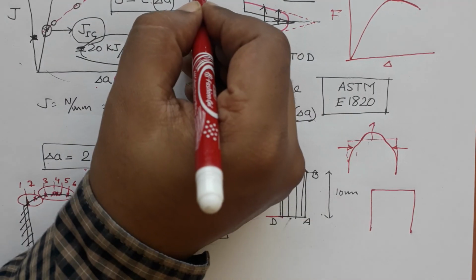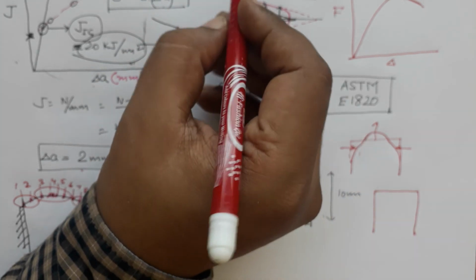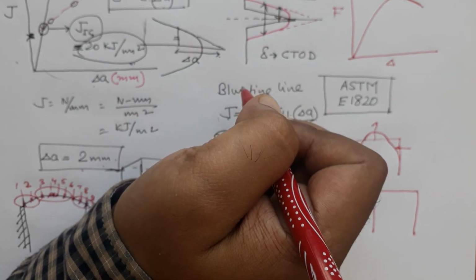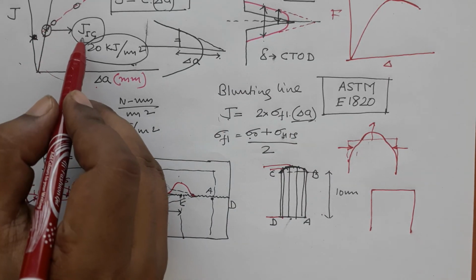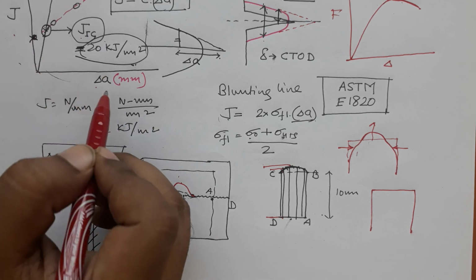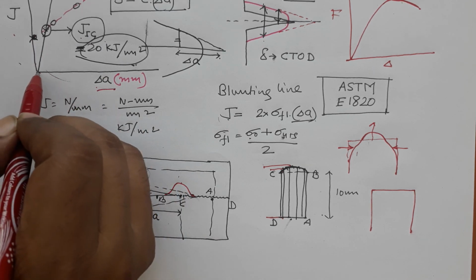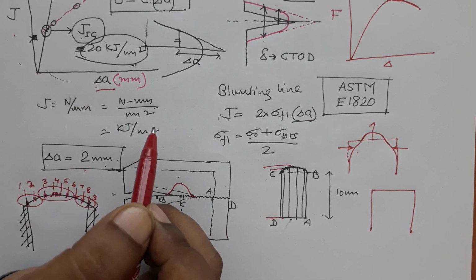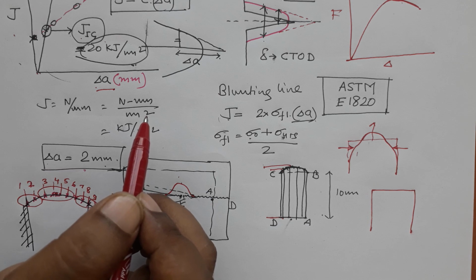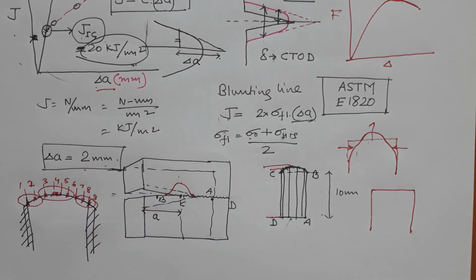In this lecture we learnt about the J integral concept, which comes from the conservative field. How do we get it experimentally? How do we calculate the experimental value of the J integral? How do we find out the J1C value from the J versus delta A curve? And we learnt it by doing or testing several different specimens at different crack lengths. In the next lecture probably we will have a look at how we can, or if we can, do it using one specimen, okay.